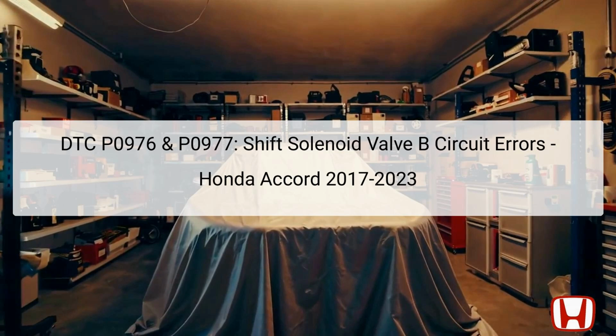the transmission. The shift solenoid valve is crucial as it controls the flow of transmission fluid, thereby impacting the vehicle's ability to shift gears smoothly. Its proper functioning is vital for efficient transmission operation. The solenoid and its circuit components are located within the transmission assembly and are typically accessed through the transmission fluid pan or housing. Accurately diagnosing these trouble codes is essential to ensure the longevity and performance of the vehicle's transmission